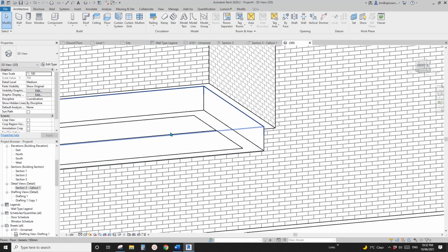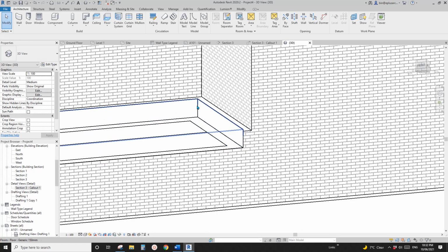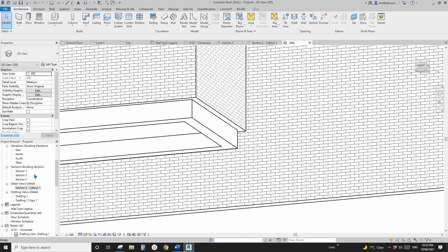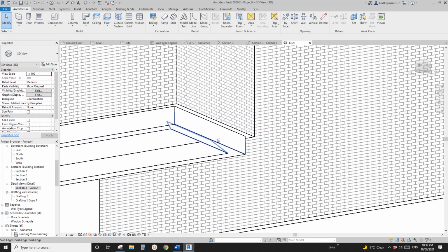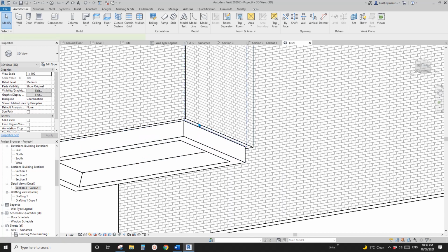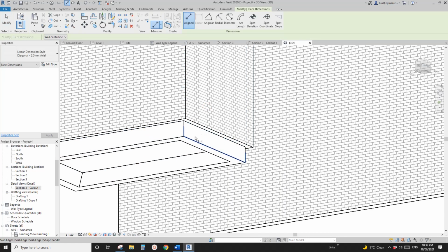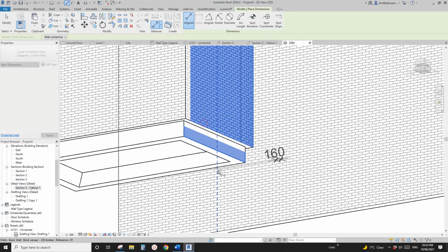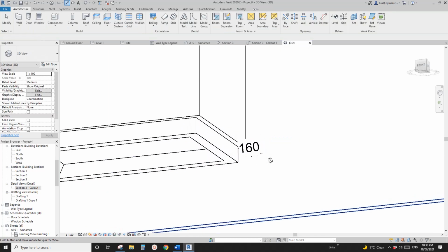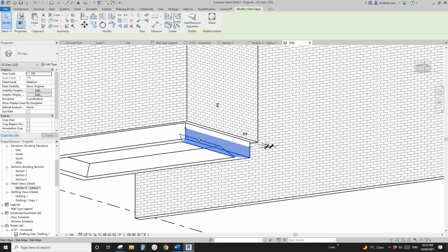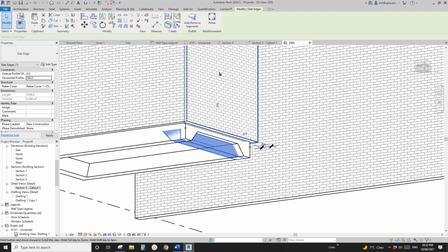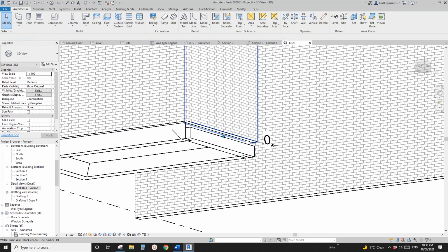this wall face, so I don't need to do the rebate. So I'll just use this profile. So I'm going to check the offset. So you can do it in 3D view. You can dimension in 3D view if you wanted to. So see, that's 160. So now I know that if I do horizontal offset 160, maybe negative will go along to this wall.